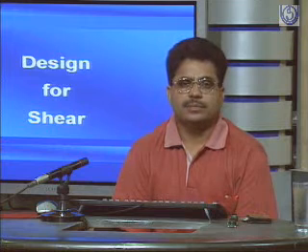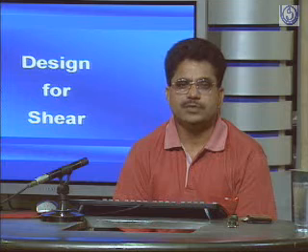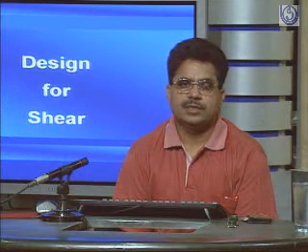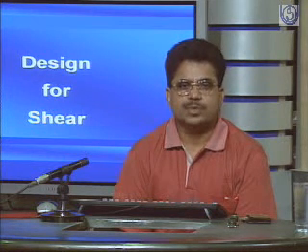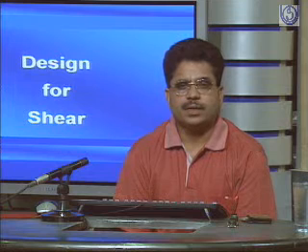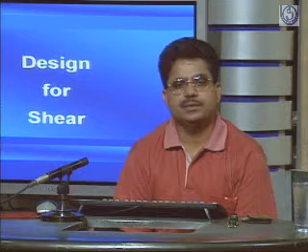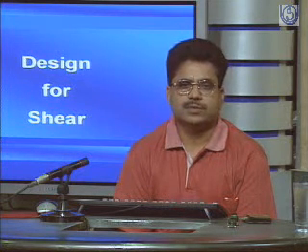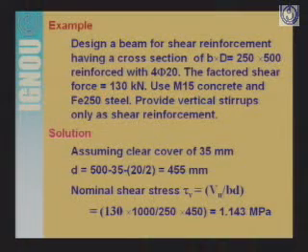Just to recall, if tau v is less than tau c, then minimum shear reinforcement will be provided. If tau v is greater than tau c, then the shear reinforcement will be designed. And of course, another comparison between tau v and the maximum shear stress was also there, and if tau v is greater than tau c max, then we have to redesign the section.